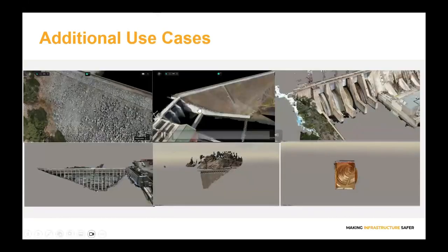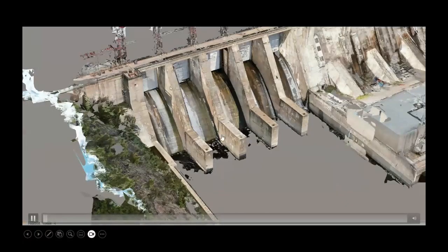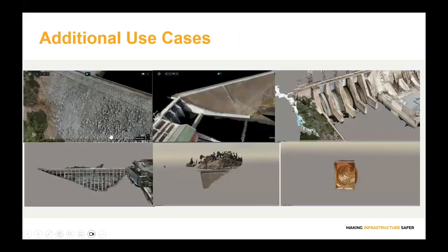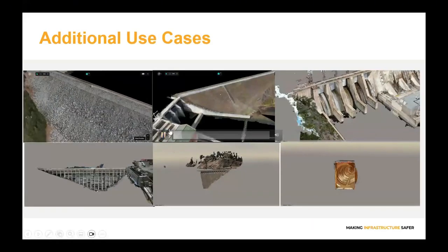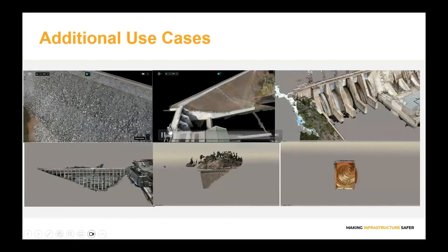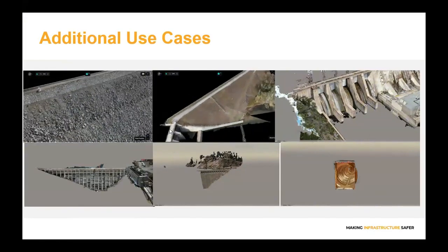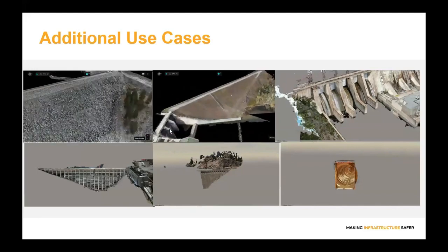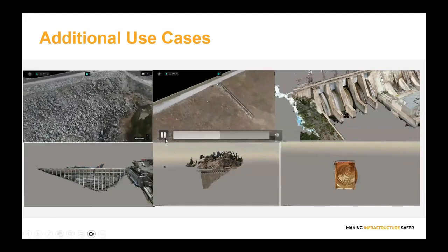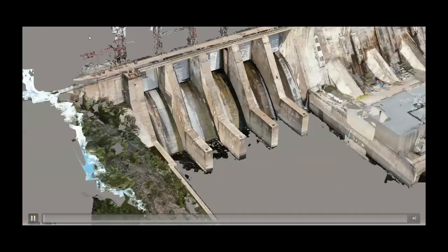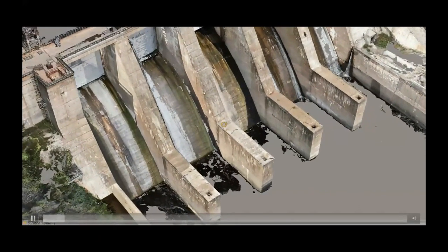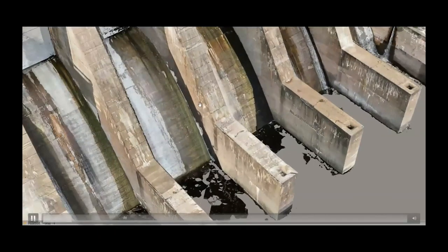And just some additional use cases before I turn it over to everybody here. You're able to use this not only on concrete dams, but also for rock fill structures for monitoring over time, earth and embankment dams to get a model of those, buttress dams, arch dams, run of river structures, and even structures like penstocks where access is challenging.